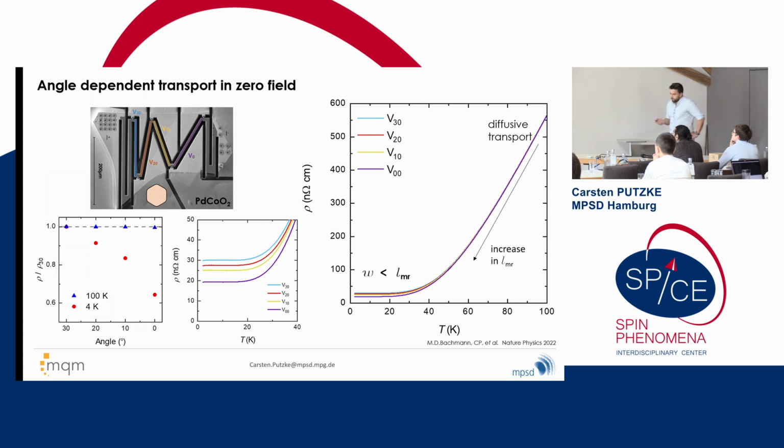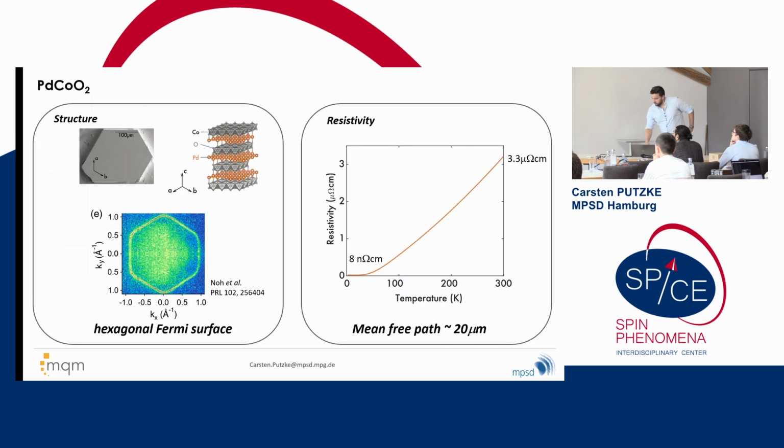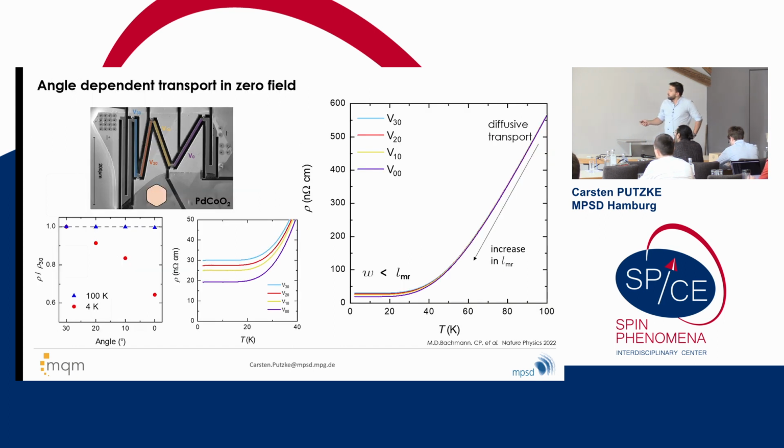And this essentially comes from the fact that if you look at, again, the Fermi surface, all your VF are perpendicular to the Fermi surface. They point all in this direction. So if you now finite size confine this object, then if I cut a current path at 30 degrees, these states here will just scatter into the surface of my channel, okay? So here, basically, VF points along the direction of the current path, and then this one, VF just points into the walls. So you get enhanced surface scattering in the plane, and you can really think of this material similar to a billiard table. And basically here, you're just shooting your ball away straight into the wall, and so it has a much higher resistivity to end up on the other side.